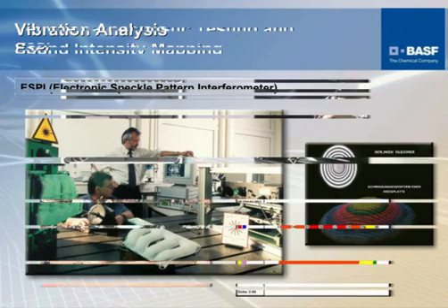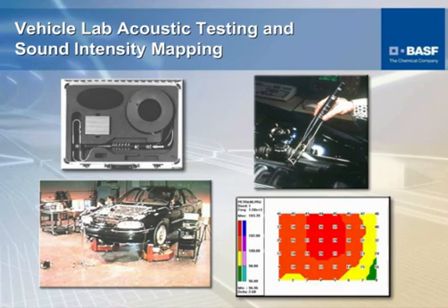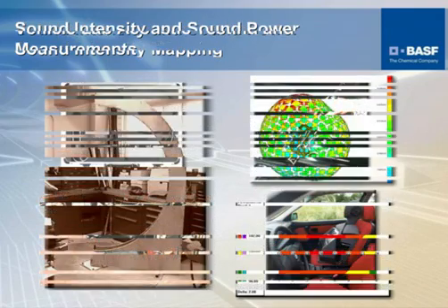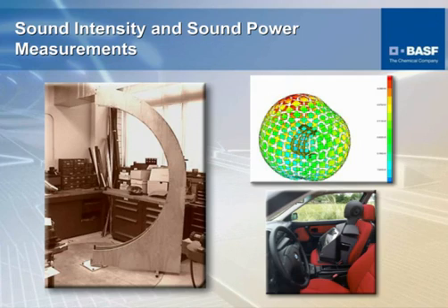We have an array of different recorded sound intensity probes to actually do sound intensity, which is done typically perpendicular to the actual grid that's laid out in this picture here on an engine. Basically, the sound intensity is used when you have a noisy environment, therefore it's easier to control the environment and to extract data that is meaningful.